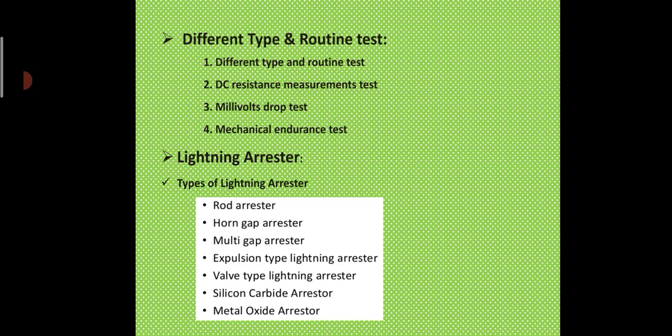Some 50 operations are activated by energizing the relay. Remaining operations are done by operating the trip circuit by other means. About 100 operations are made by connecting the main circuit in series with the trip circuit. Manufacturers may do more than 1000 operations to ascertain the mechanical healthiness of design and its quality. Modern circuit breakers and SF6 circuit breakers are practically maintenance free. So these are the mechanical endurance tests.